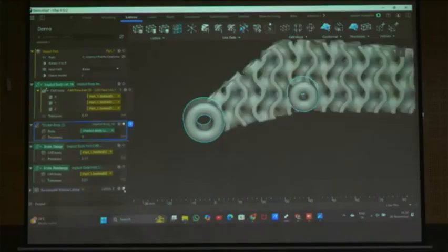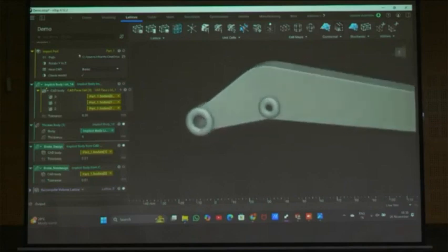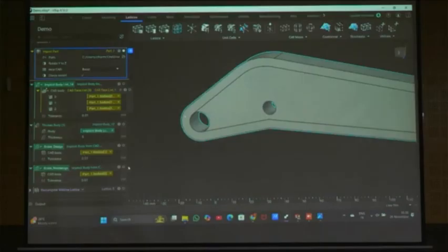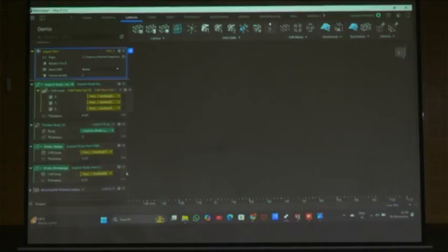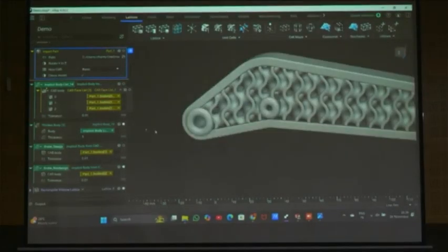Wait, we will see now. Design, right? Is this okay? Are we getting like this? See, this is the original design. This is the one we are getting, but the hole is not proper, right? So here we need to apply the intersect. Intersect means it will find the common body, right? So that we can find it. So Boolean intersect.